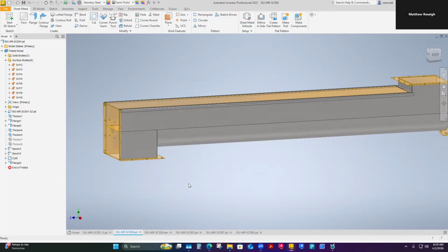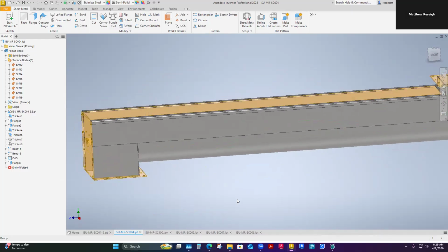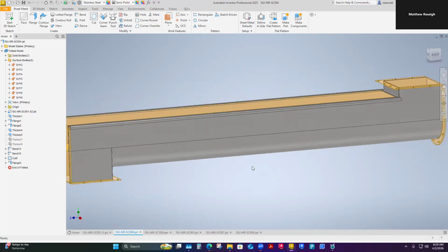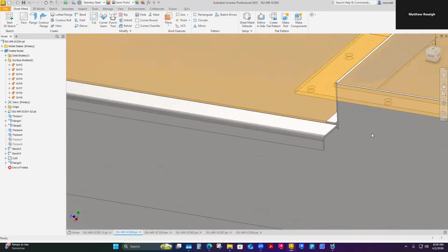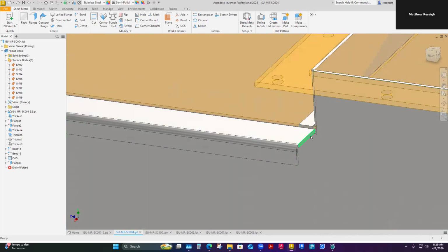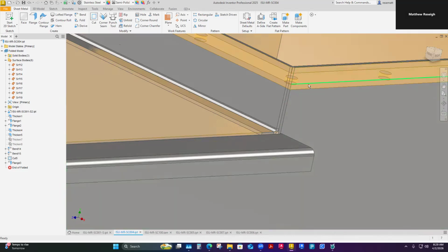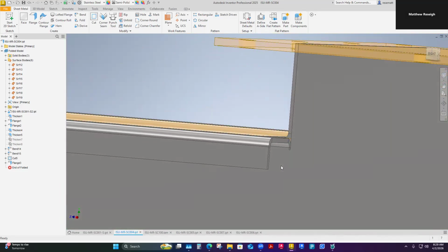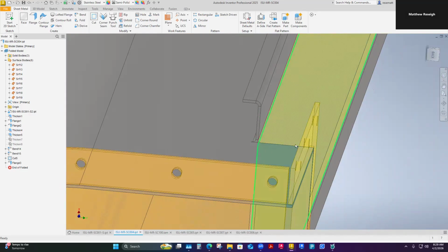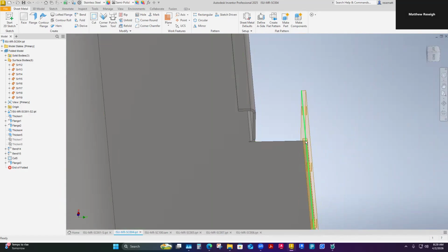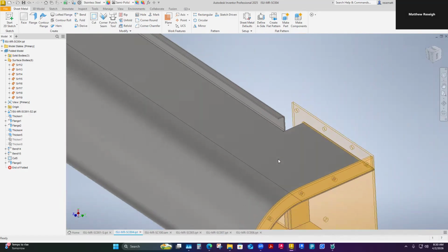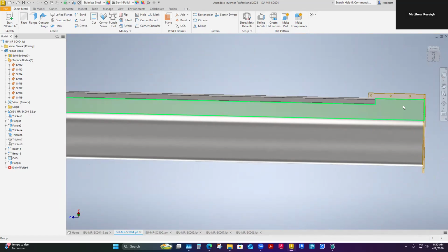Okay, so this one's pretty easy to fix, the main housing. What we have going on there is I didn't like that there wasn't a cut separation between this little flange here and what will remain straight here. So you've got to think origami a little bit. That is going to be the same flat material when it unfolds. But in order to bend it, we need to cut a relief there to allow those bends to happen. And the person that has to bend this has to not bend that, but bend this.